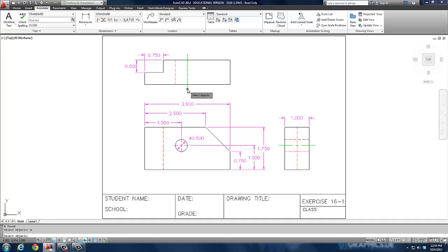So I'm going to move from this point, move, pick the center line, enter, from this intersection. I'm going to tell it to go a quarter. Come on, like me. Oh, it's still on rotate. Move. There we go. Now it likes me. From that intersection straight to my left, 0.25 inches because it is a 1/2 inch diameter. So there it is in the center. That's all it takes. This one's done.